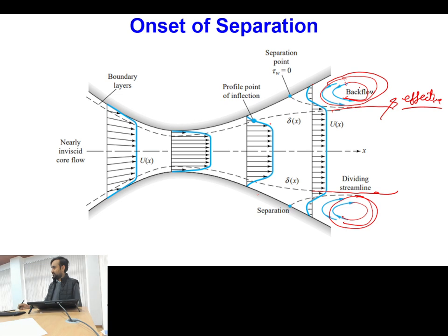Okay, operational cost will be high. Second important application of this comes in actually design of wind tunnels. In wind tunnels, what we have? In order to achieve the Mach numbers greater than 1, first we have a converging section, and then after that converging section, ultimately we have to discharge that air to the surrounding atmosphere. Okay, so for that we have to have one diffuser section.